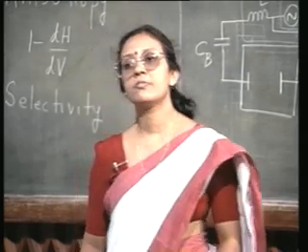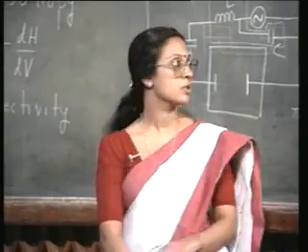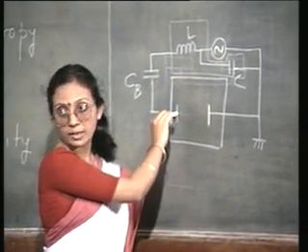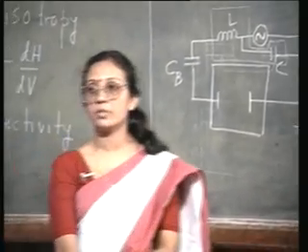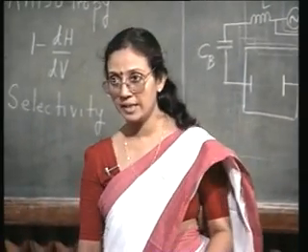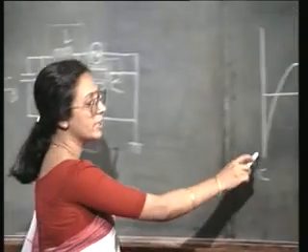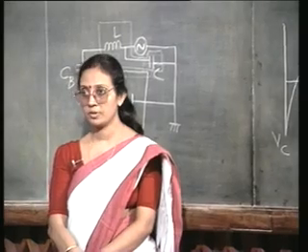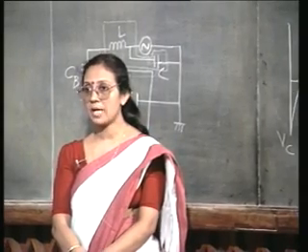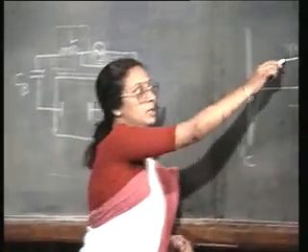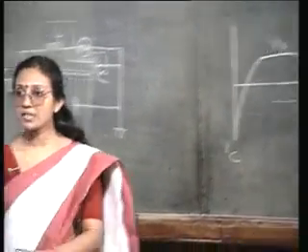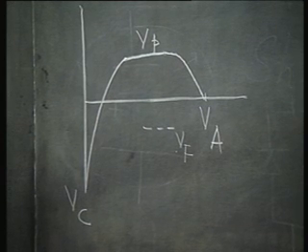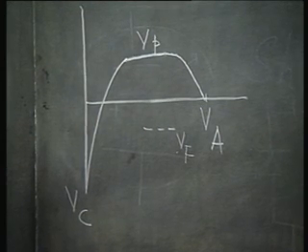However, if you place your substrates on this other electrode, the RF powered electrode, which is commonly referred to as the cathode, then since there is a very high negative sheath potential developed between that electrode and the central portion of the plasma, you have a large potential difference, and therefore, the ion bombardment energy will be very high.